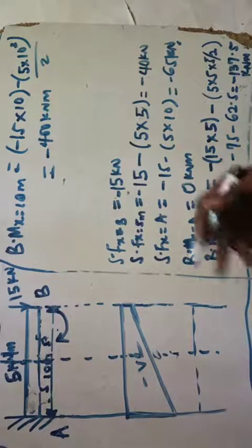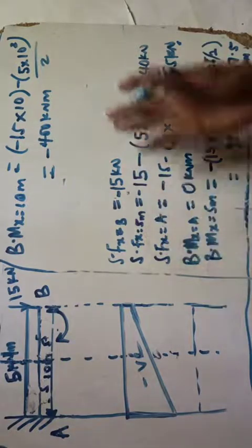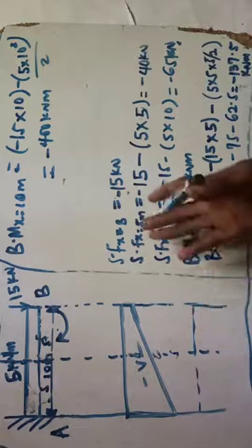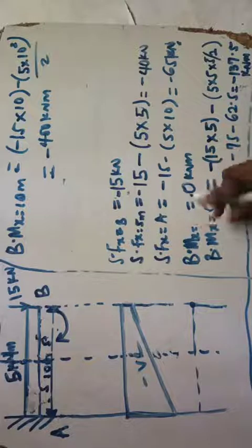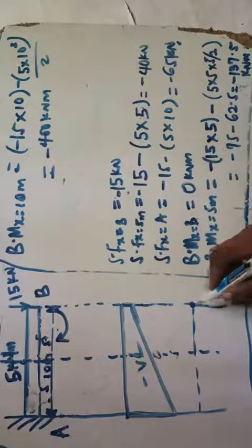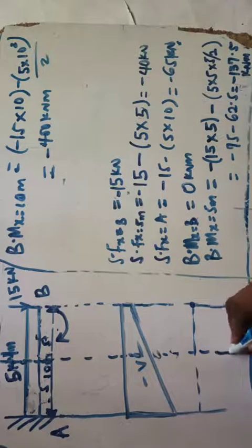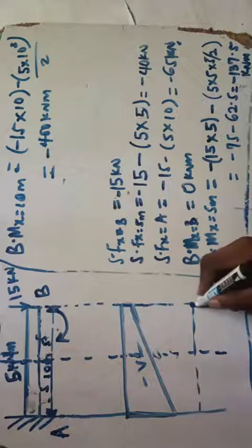Now the bending moment, you can just even draw the bending moment. The bending moment will be something also bent. You remember the bending moment. So let's see. Here you have the bending moment towards 0, and not at A, rather this is at B, sorry, at B 0, and at x equal to 5 meter you have it as minus 1735.